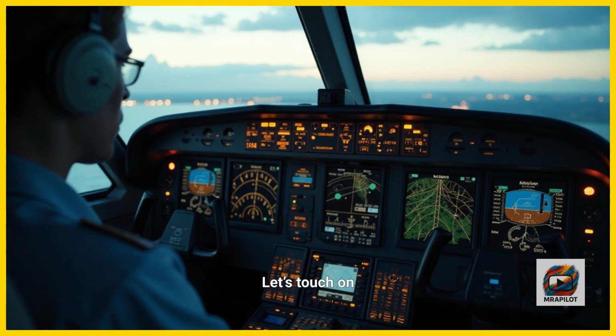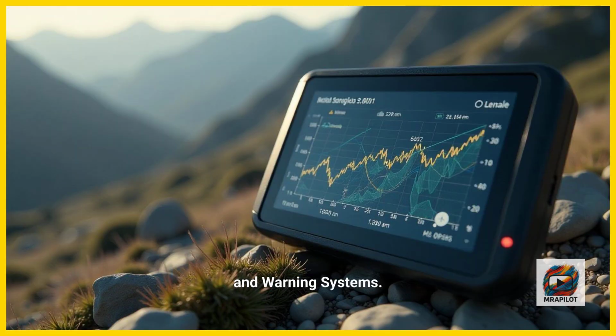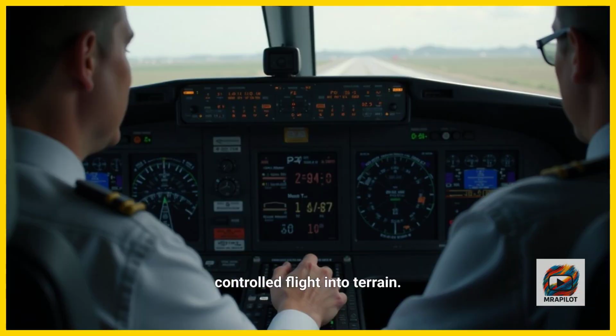Let's touch on TAWS, terrain awareness and warning systems. These use GPS and a terrain database to predict if the aircraft is at risk of controlled flight into terrain. They work best when barometric and GPS altitudes match expected values.